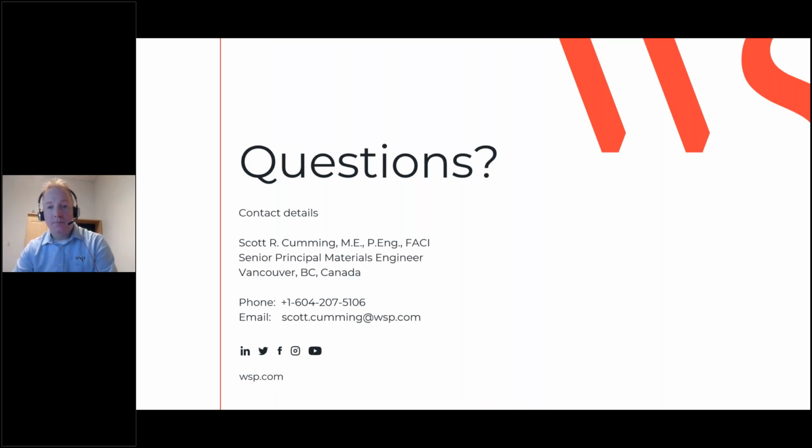Thank you. The next question is, are there any up-to-date studies on the variance in embodied carbon of mixes between different regions? Certainly, the ones that I've put in the links are probably the best ones right now for the different geographic regions in Canada. Those were done, I think, based on 2020 to 21 data, and were produced in 2022. But for an EPD to be valid, they do need to be updated every 5 years.